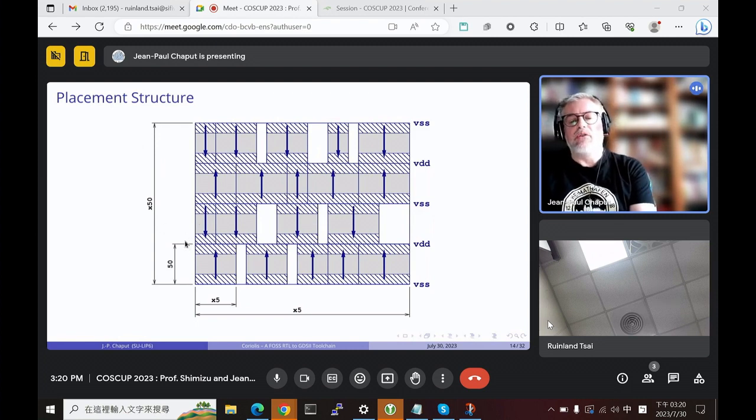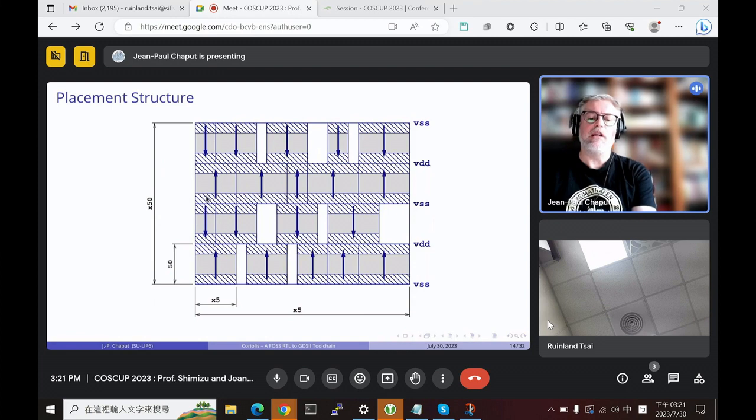And so in the Y coordinate, in the vertical coordinate, you have to respect a certain pitch, and it's the same horizontally, but it's a smaller pitch. So you get more leeway in the horizontal direction than in the vertical direction. This is the work of the placer. The placer is tasked to do that with some other accessory goals, the first one being minimizing the wire length.